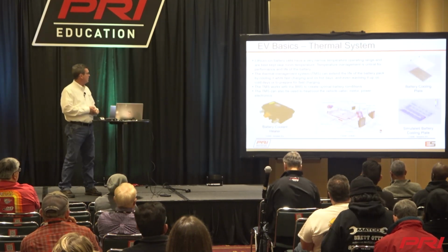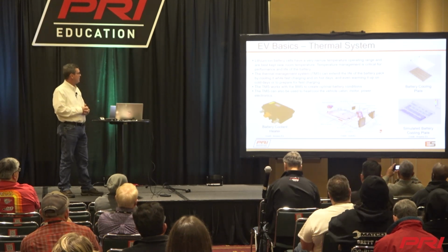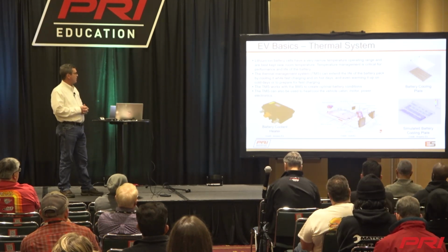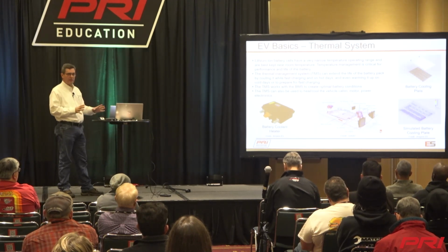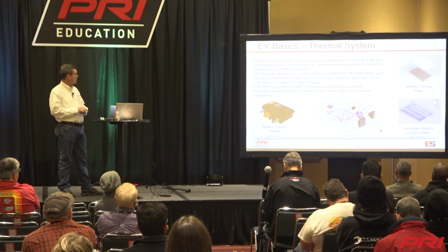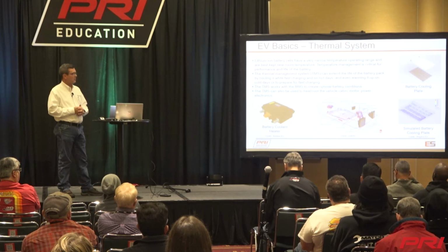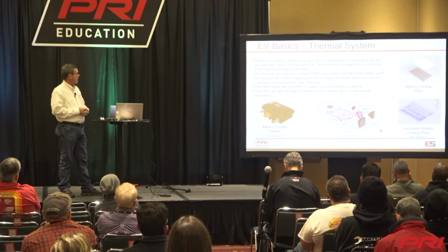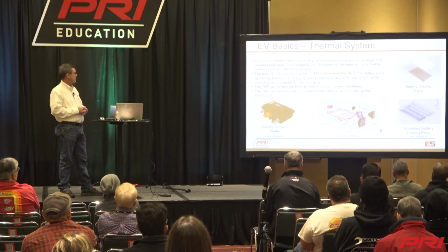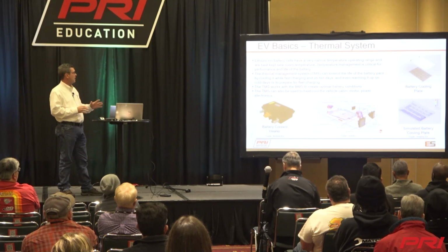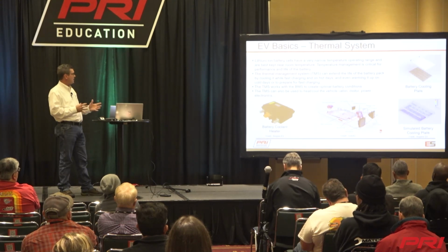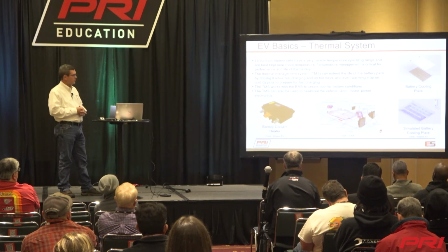Thermal systems. The lithium-ion batteries, which is mostly what we see now, have a very narrow temperature operating range, and they're best kept near room temperature. It's kind of a Goldilocks thing where they don't want to be too hot, they don't want to be too cold. We all see in the news almost weekly what happens when they get too hot. The temperature management is very critical. So this thermal management system, the TMS, can extend the life of the battery pack by cooling it while fast charging and on hot days, and even warming it up on cold days, or to prepare it for fast charging.